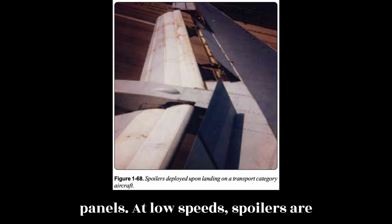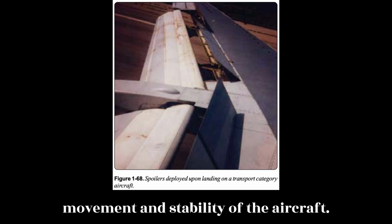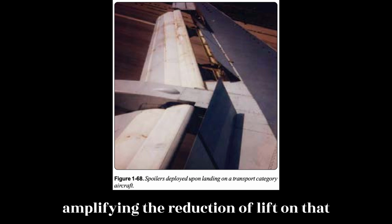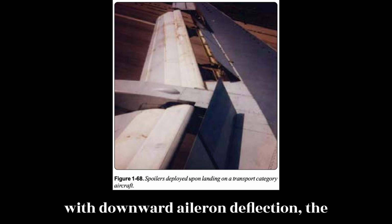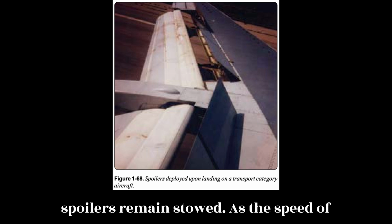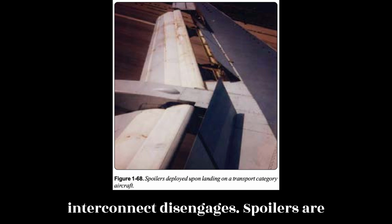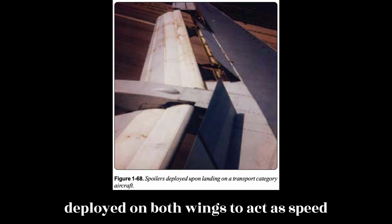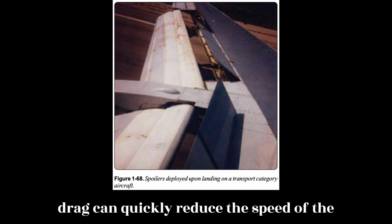At low speeds, spoilers are rigged to operate when the ailerons operate to assist with the lateral movement and stability of the aircraft. On the wing where the aileron is moved up, the spoilers also raise, thus amplifying the reduction of lift on that wing. Figure 1-68. On the wing with downward aileron deflection, the spoilers remain stowed. As the speed of the aircraft increases, the ailerons become more effective and the spoiler interconnect disengages. Spoilers are unique in that they may also be fully deployed on both wings to act as speed brakes. The reduced lift and increased drag can quickly reduce the speed of the aircraft in flight.